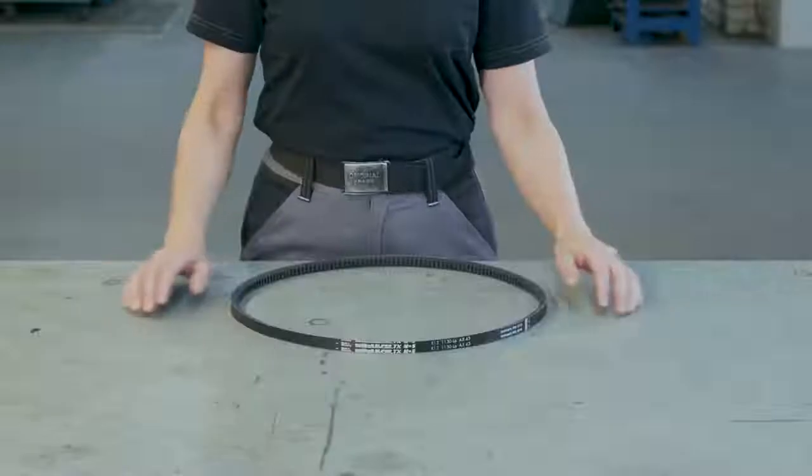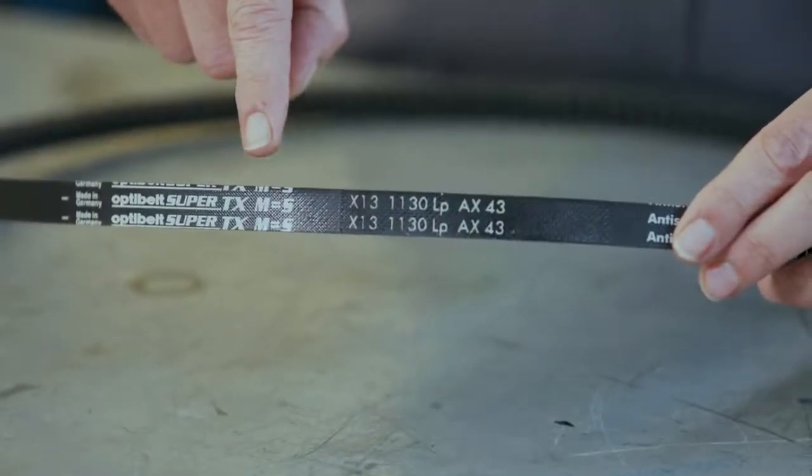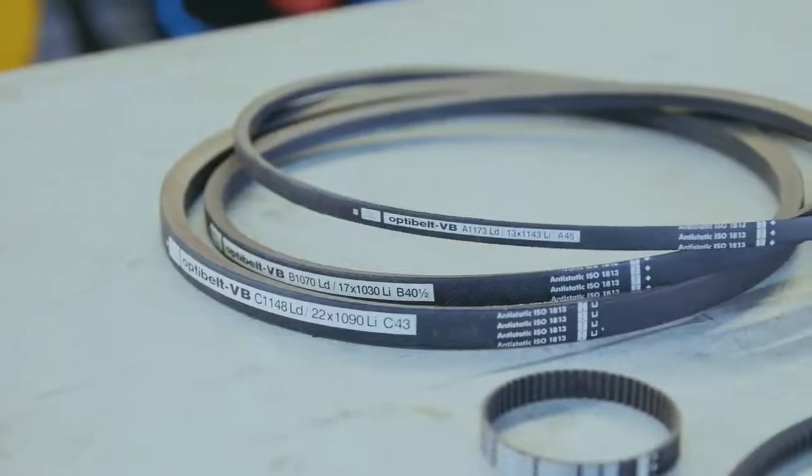Lastly, I want to highlight the importance of having matched sets. When you're dealing with 2 V-belts with the same size designation from different manufacturers, actually, even when they're from the same manufacturer, in practice you might find some variation in length. If you're using single belts on your machine or application, then this should not be an issue. However, if you're running multiple V-belts together on the same drive, then having belts of the same length is very important. If you don't have belts of the same length, efficiency will decrease dramatically.